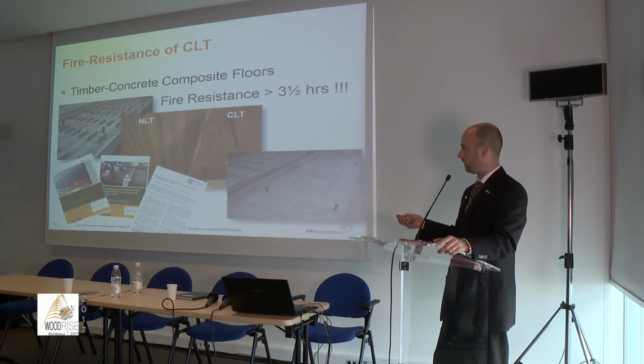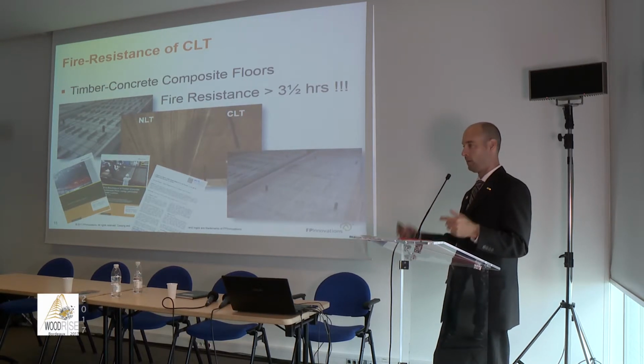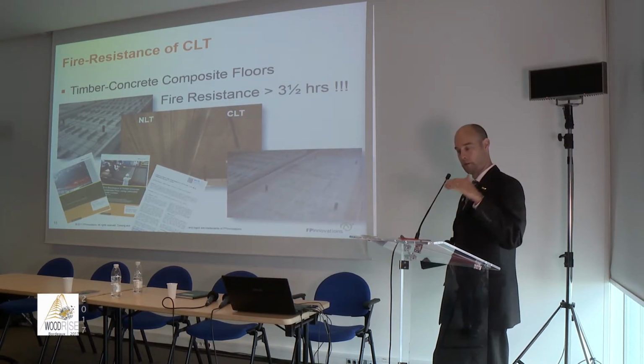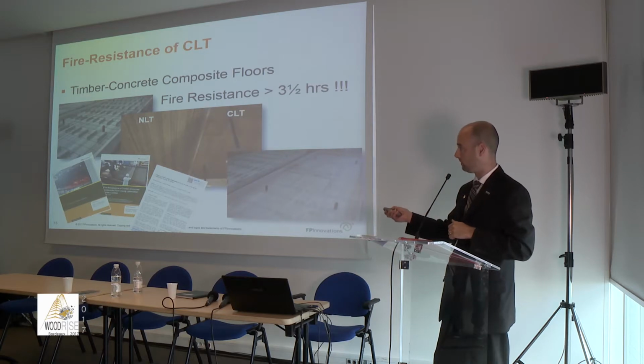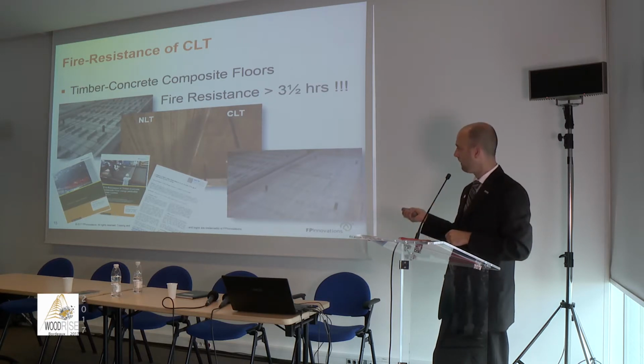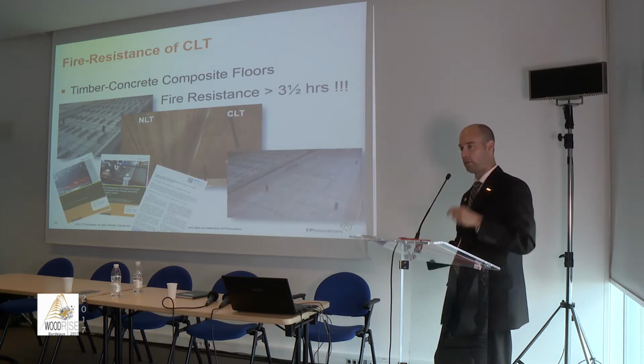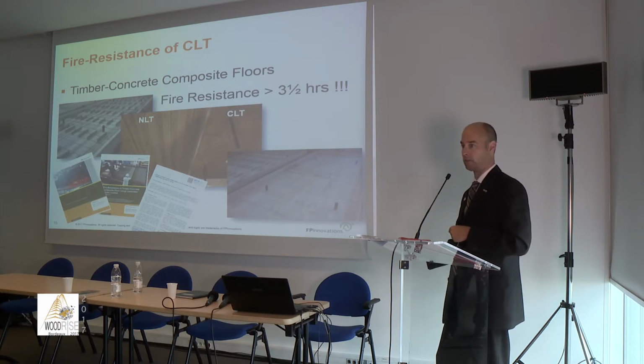We tested nail-laminated timber, so just 2x6, 38 by 180-something millimeters, nailed together with single truss plates, metal light gauge steel truss plates that were embedded in it, and we just poured the concrete. We also tested a CLT element, a 5-ply CLT, where we used 45-degree self-tapping screws as shear connectors.